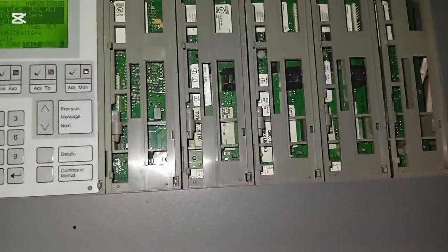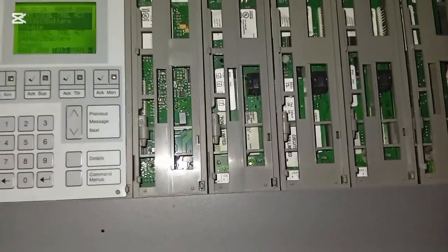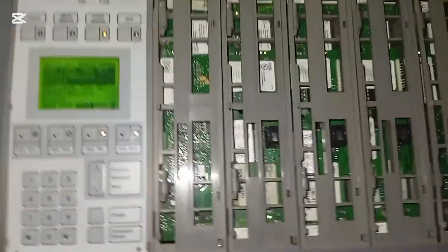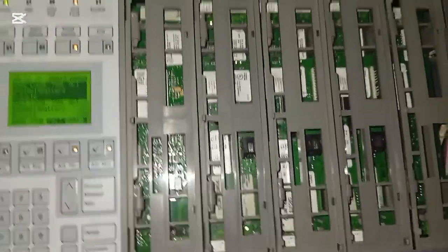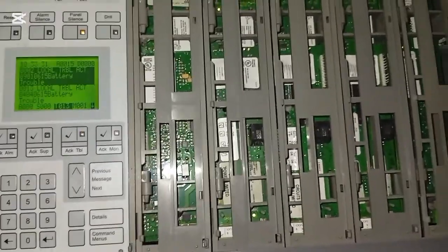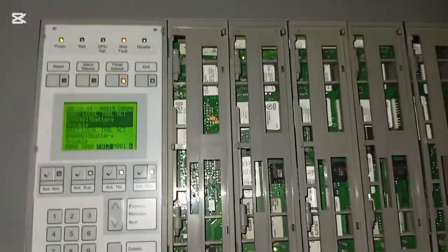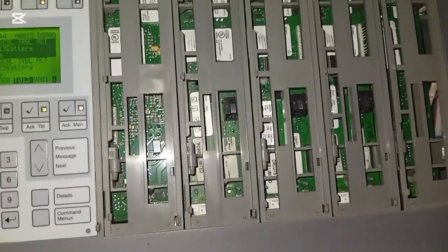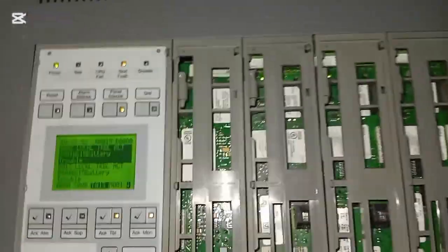There is a power supply which provides 24 volts DC. So in case of a blackout, there is a provision for backup power, and for this backup power we use batteries. When these batteries are depleted, or have died or failed to accomplish their task, they will come up as an error, because their internal resistance has increased and they can no longer provide the required current. In that case, the battery will come up as a trouble.